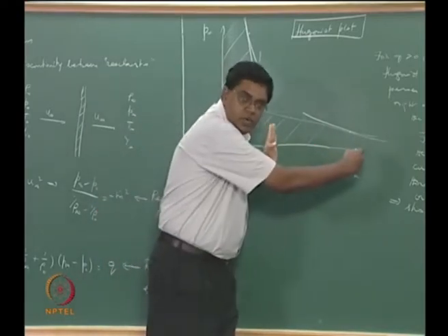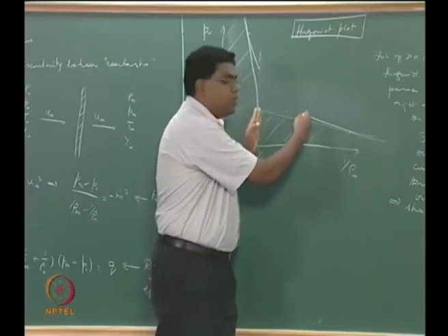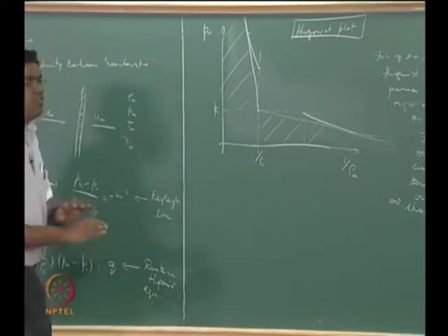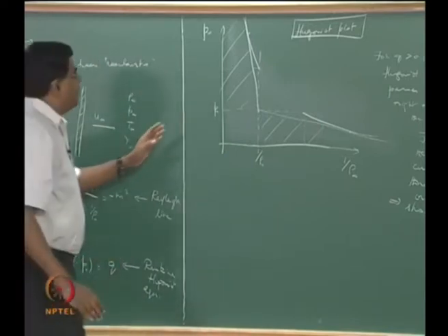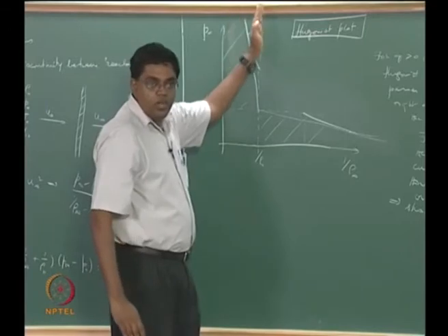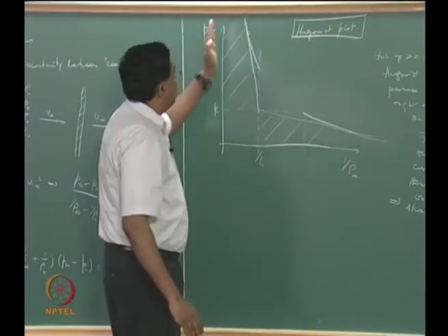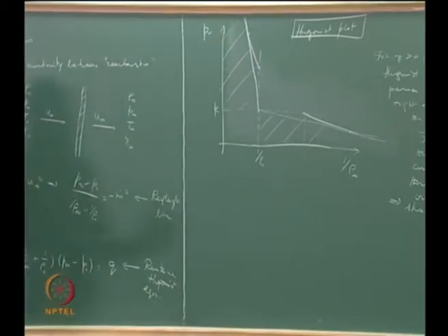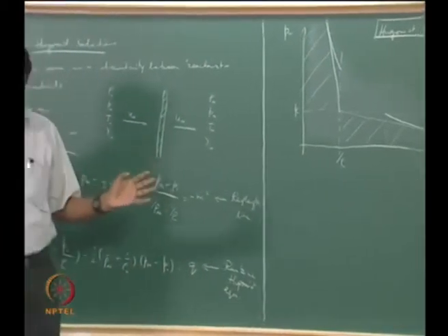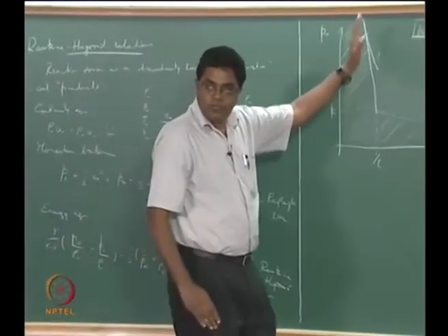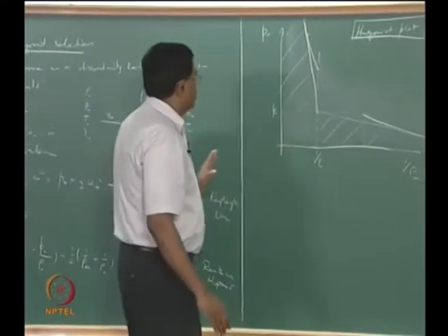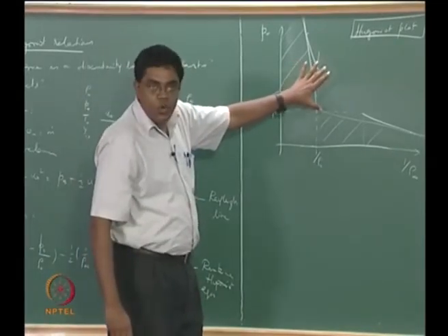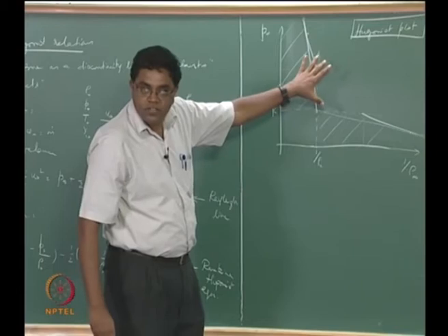There is a significant amount of expansion that's going on right from the beginning because of the heat addition, and then nothing until you get to very fast waves, and you can now get these very fast waves to go all the way to the other limit where you are getting close to an isochoric process, that is like a constant volume situation, right. And there again, because of the heat addition, you hardly have any change in volume, but essentially the pressure increased, right.